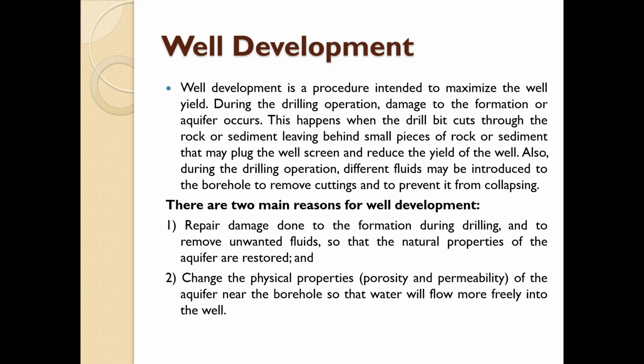Now the well development. Well development is a procedure intended to maximize the well yield. During the drilling operation, damage to the formation or aquifer occurs. This happens when the drill bit cuts through the rock or sediment, leaving behind small pieces that may plug the well screen and reduce the yield of the well. Also, during drilling, different fluids may be introduced to the borehole to remove the cuttings and to prevent it from collapsing. So there are two main reasons for well development.